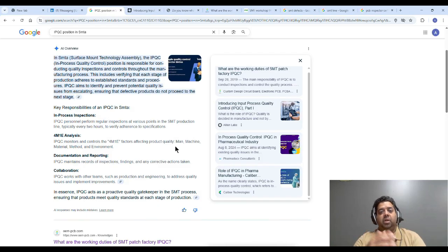So you need to figure out how to do the process engineering and improve processes as you go along. That includes what pressure and time you're using for a squeegee. That's part of process engineering. Optimization of your pick and place program is also method. Thermal profiling comes under method, and all these things are method.